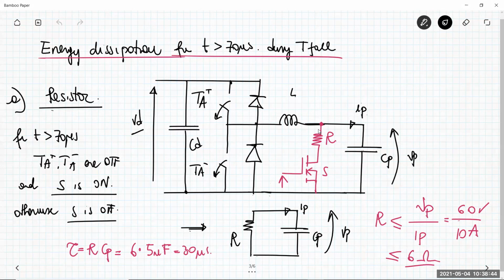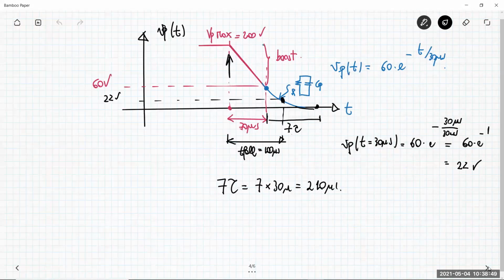And basically this solution does not permit to have the rest position of my injectors after 100 microseconds. So we have to wait some time constants for this voltage across the injectors to be completely zero. Sometimes you can find applications in which you cannot recover the energy and dissipate it in the resistor. Pay attention, because you can have some drawbacks in terms of power dissipation and in terms of timing of your system.